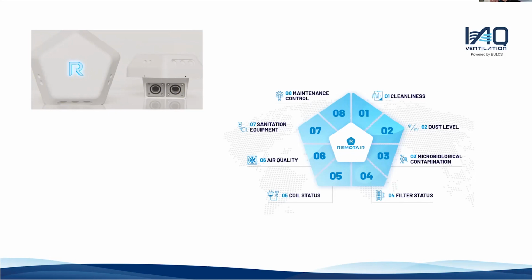and shows you what's happening in the ductwork, unless you go to clean or you put a robot into the ductwork and it shows how your ductwork is. This one is another type of system that you can actually place into your ductwork, and it will have the ability to look through 360 degrees movement at the cleanliness, the PM 2.5s, again the microbial content, if the mold growth is there due to condensations and such, filter status, your coil, and indoor air quality, which we've been talking about, filtration and maintenance.